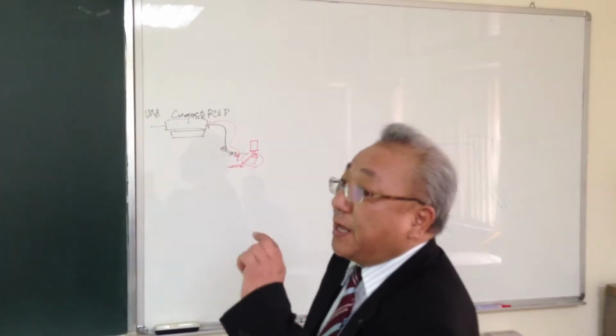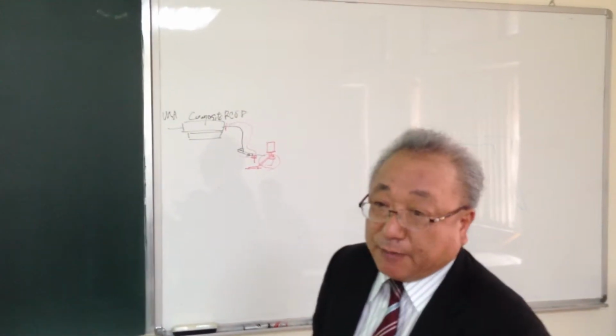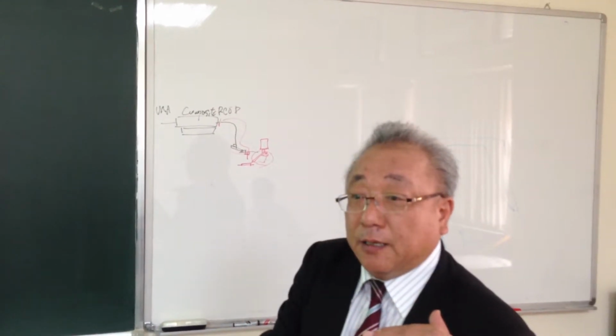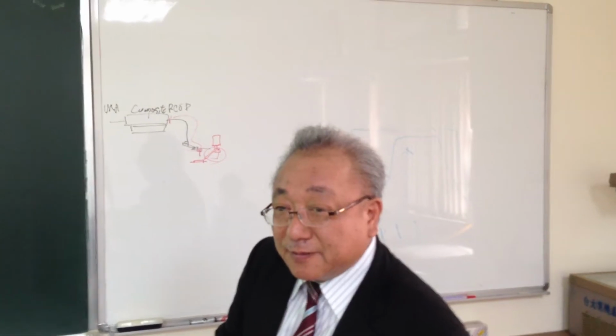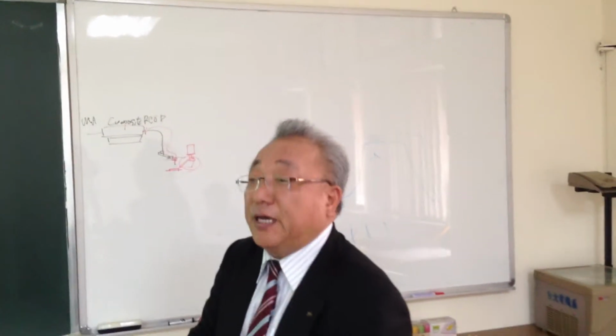Noise figure value error depends on the mismatch between the test port and the DUT. So sometimes the device is not 50 ohm. In that case, the DUT's mismatch is big.